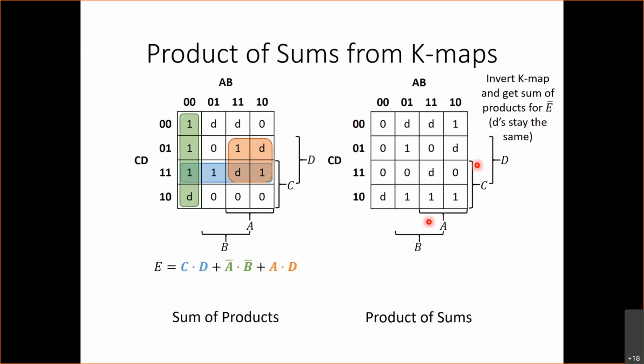And now that we have this Karnaugh map, we are going to draw rectangles over the ones in this Karnaugh map. So the first rectangle is over here. We can find that this entire row can be covered with a rectangle. And there's an important observation here, which is we can use the same D for both the sum of products and the product of sums.